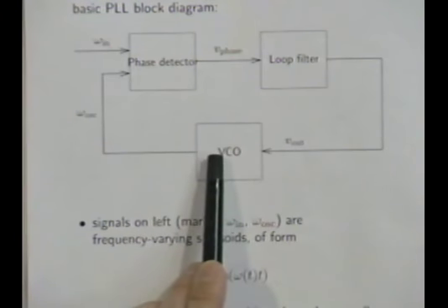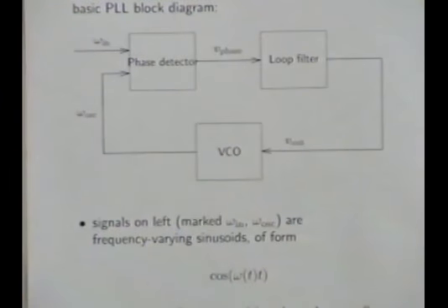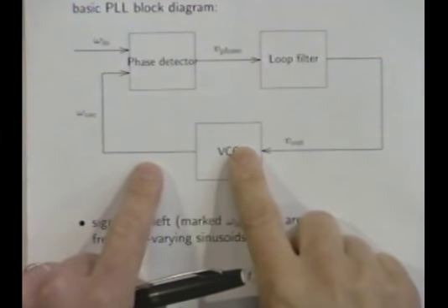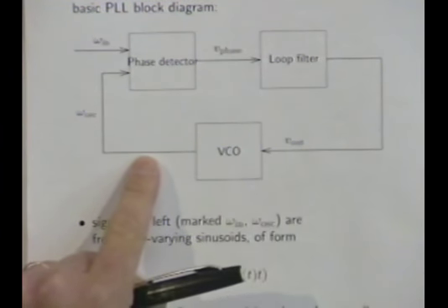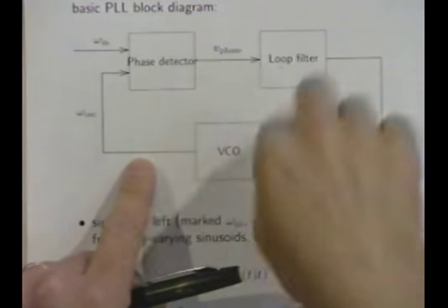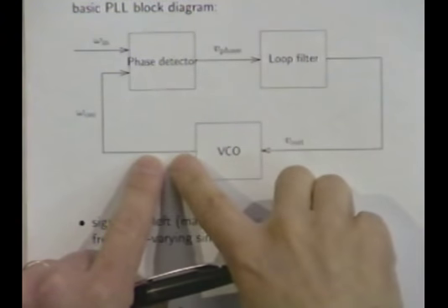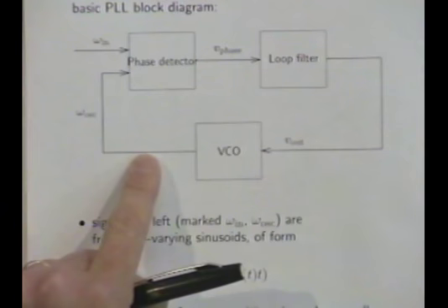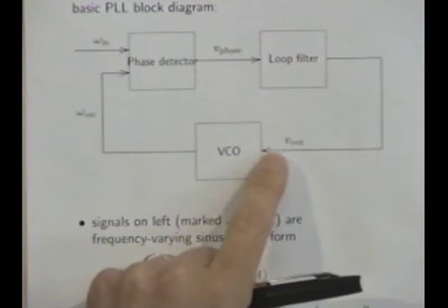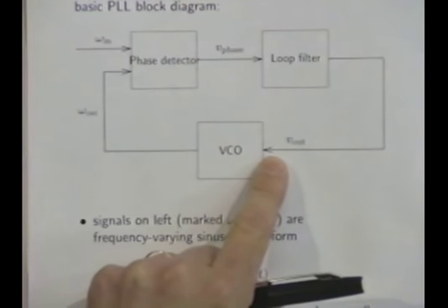Okay? Now, in many applications of phase lock loops, the ranges of frequencies we're talking about are measured in sub-fractions of a percent. Okay? So in other words, if you were to just casually examine this circuit, this would look like an oscillator. You couldn't look on an oscilloscope and see that the frequency was varying. Although there are PLLs which have a wide lock range, normally, the frequency here varies only just a little tiny bit, like that. So this varies, and it's modulated by this voltage here.